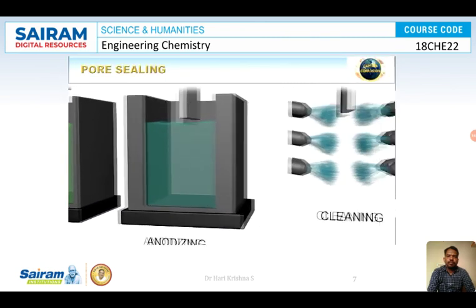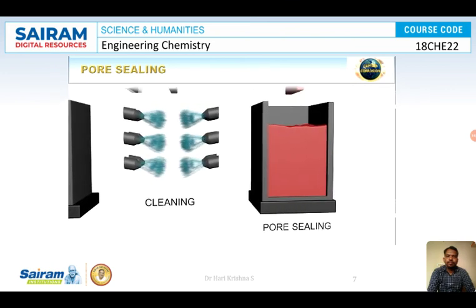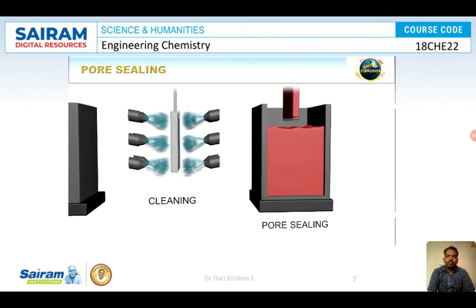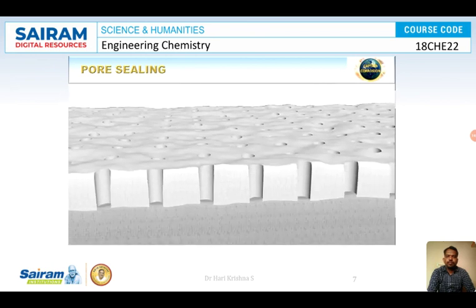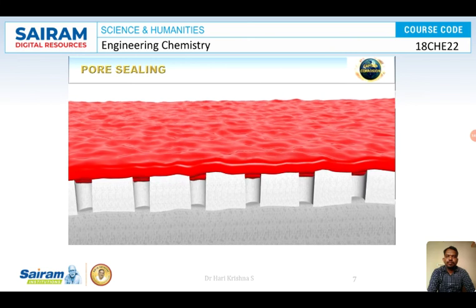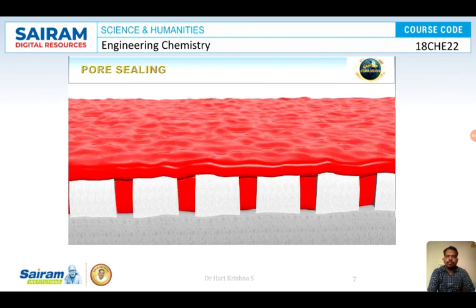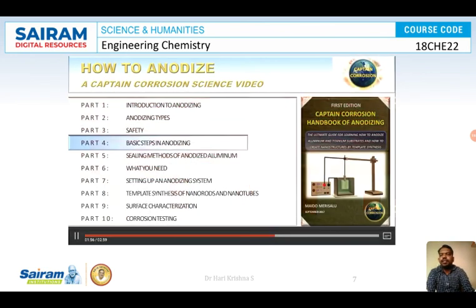Finally, the pores in the anodic aluminum oxide layer are normally sealed to achieve long-term protection against corrosion, improve the resistance against mechanical damage, or to simply apply an aesthetic appearance. This can be done, for instance, by hydrothermal sealing, paints, or a variety of alternative methods, which will be discussed in the next episode. So these anodized articles, where are they used?